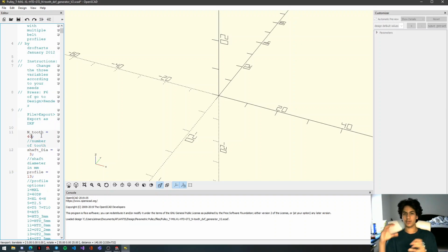So when you belt a smaller pulley, which is 34 teeth, to a larger pulley, which is 40 teeth, that'll reduce the gear ratio, because we have a 13.71 motor that we're going to be using, but I think 13.71 is way too fast of a ratio. So we're going to just gear this up to a ratio that's much easier to manage.